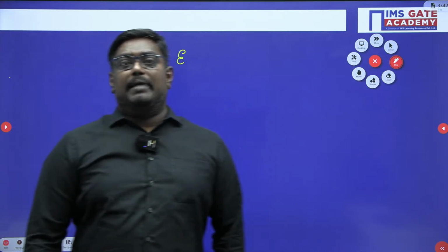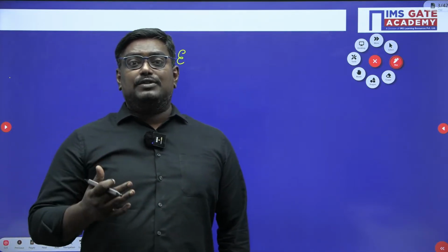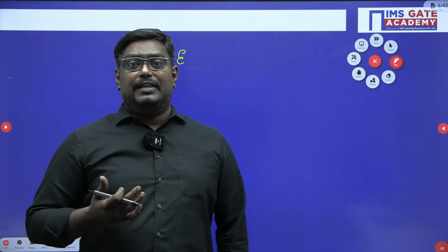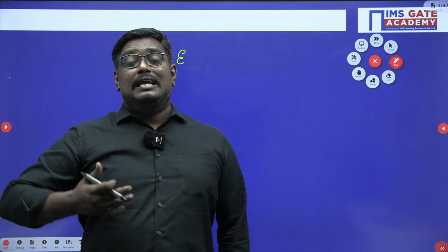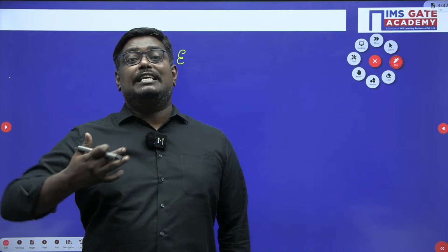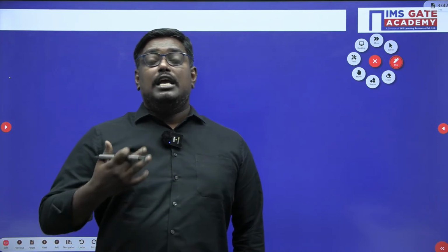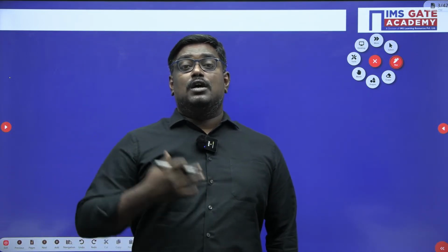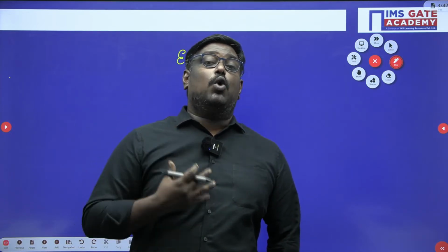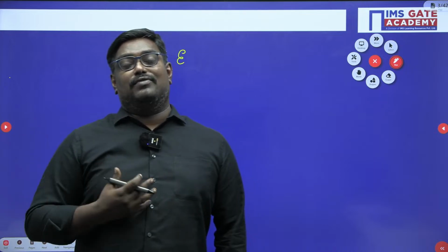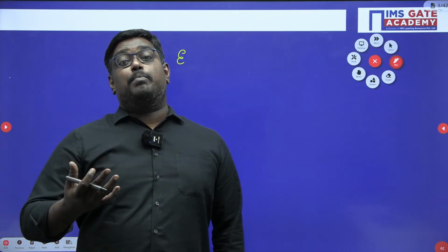Now, what do you mean by effective stress? Effective stress is the intergranular pressure between the soil particles. It has a measurable influence on the engineering properties of the soil. Total stress is due to the self-weight of the soil or due to the overburden pressure, or you can say earth fill. So what do you mean by pore water pressure again?